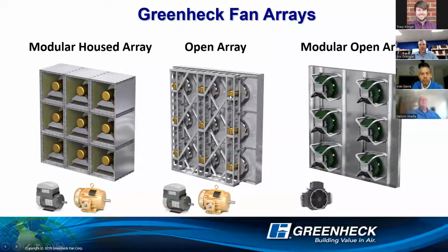So basically, just to wrap this up, different types of fan array applications, whether it's housed fan array or an open array. And then when you get into open arrays, you've got one piece designs versus modulars that are easier for retrofit applications, and then different types of motor technology and control sequences that would go with each of those. In Greenheck's case, on both the housed and the open, we can do either induction motor or an EC motor, and then the modulars are all EC motors just because they're a little bit lighter weight than the induction motors.